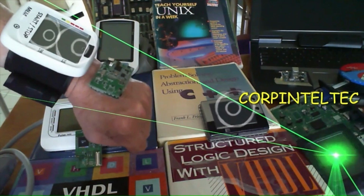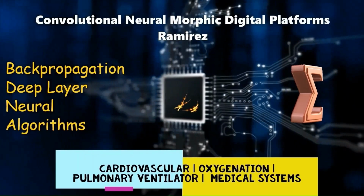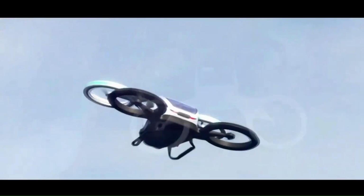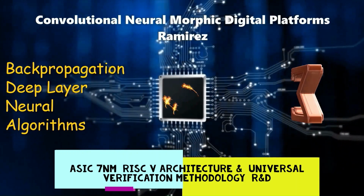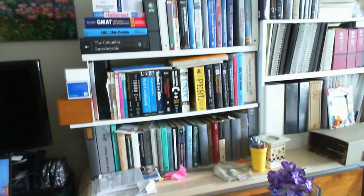At the LVS, each segment is built with OpenLane, which will check LVS for each segment of the project. Then I combine all the projects together to run a top-level LVS and DRC for routing, power supply, and macro placement.